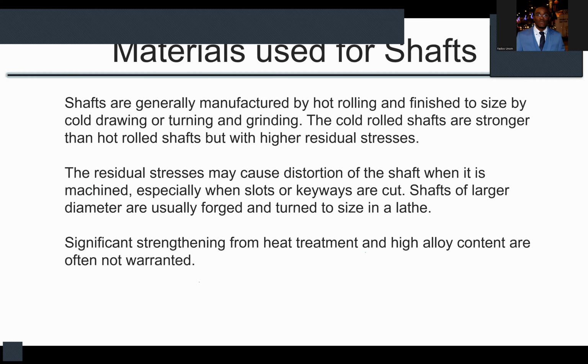Now, when you finish working on that shaft, if you are cold drawing, it means you hold both ends of a piece of steel and you pull it apart, you draw it with a large force, and in drawing it, it is stretched out. That's what is called cold drawing. As it stretches, the diameter becomes less and less.